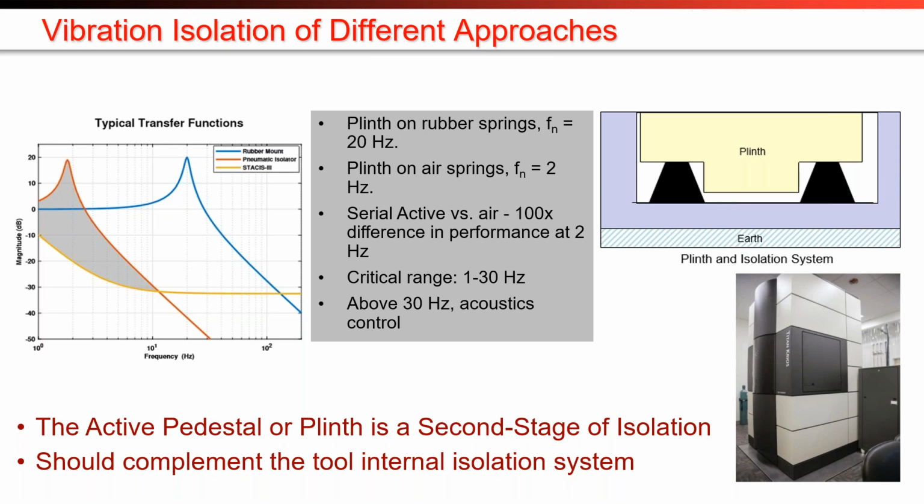And there are two reasons that that's not really important. One is that at frequencies above 20 or 30 hertz, floor vibration coming up is really a non-factor, because at those higher frequencies, we're always seeing the environment controlled by acoustic coupling or self noise in the tool, or mechanical coupling. Vibration isolation above 30 hertz for these kinds of applications is not really relevant.